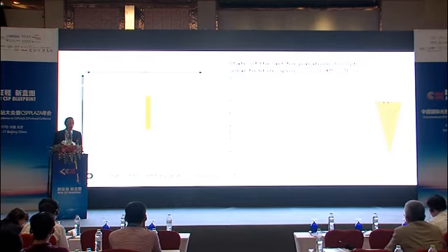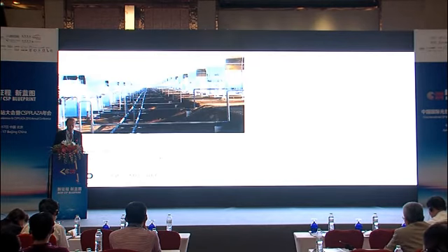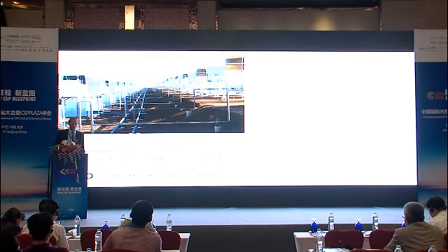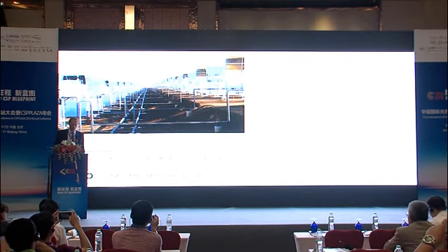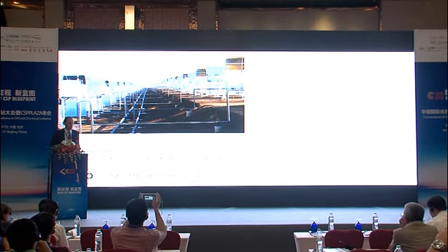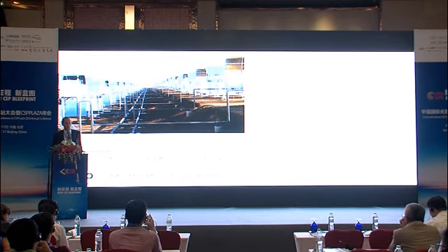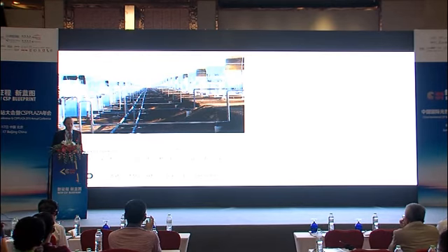And especially the collector on leveled ground is quite expensive, and I want to go into detail on that for a specific site. So that's what we usually do: we assume that the collector has to sit completely flat or with only a very slight inclination. If you have a site that is not flat, and to find a site so flat that you don't have any terraces and earth movement over a 1.3 kilometer, 2 square kilometer plot is quite rare or never. So you always end up with terraces. The terraces lead to several effects and are quite costly.